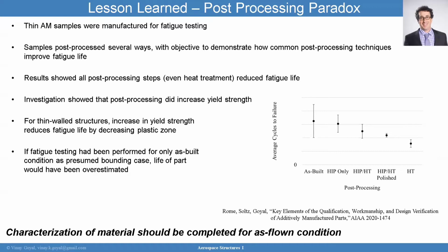So if you do one test and you're trying to validate a model, you say, oh, I'm off by 6%, so I'm going to change this in my model so I predict the failure correctly. Well, do you really want to do that? Because you don't know if the next test might be 5% high or 5% low. And Vinny knows this.